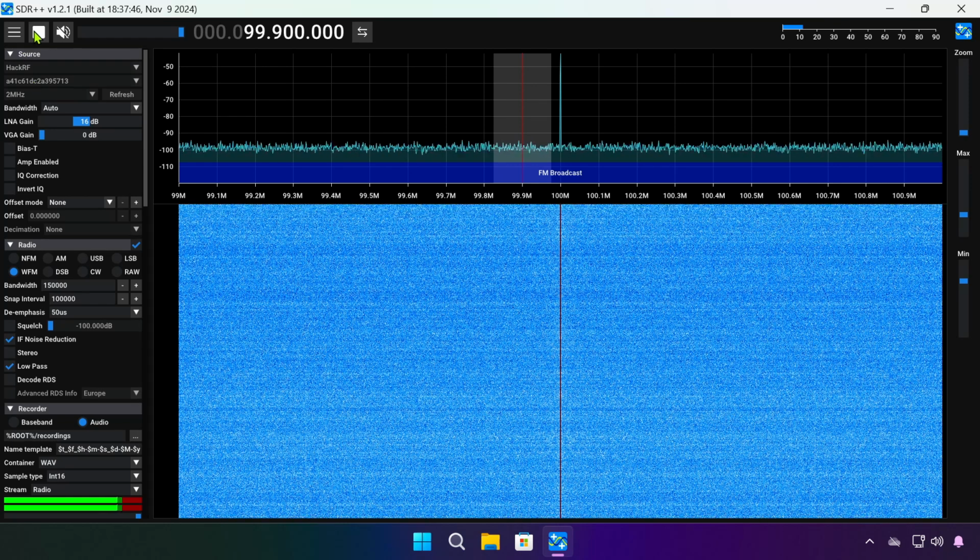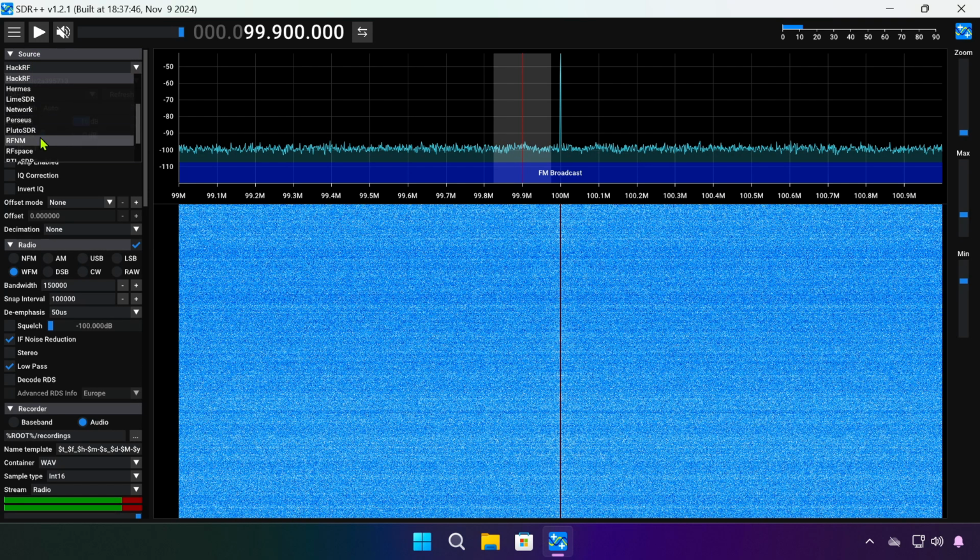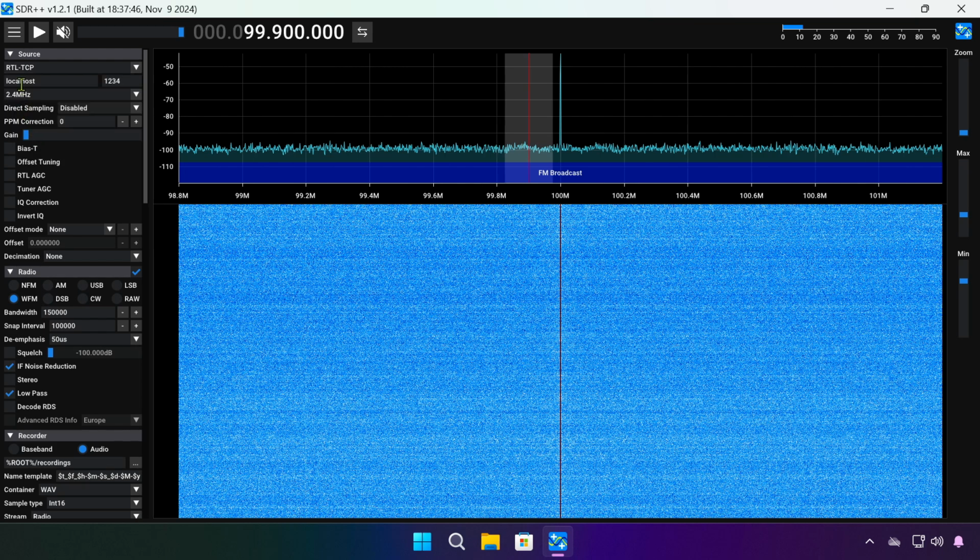For HackRF, we don't have the offset mode, but for RTL-SDR, you can say offset tuning. Now, there are available converters for these offset modes like SpyVerter, Ham It Up, DK5AV X-band converter, Q-band satellite LNAs, which are used as down converters. Now, let's talk about IQ correction.